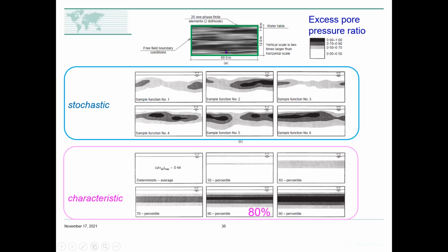So what we've done is we rolled the dice and we said, okay, we have a set of populated our finite element mesh with a set of properties that matches our standard deviation, our averages and so forth. And we then run the earthquake at it. And we predict this pattern of excess pore pressures. So the excess pore pressures are now scaling. So when you're dark black, you've got full liquefaction. So here we're running an RU of whatever that is, about 0.8 there.